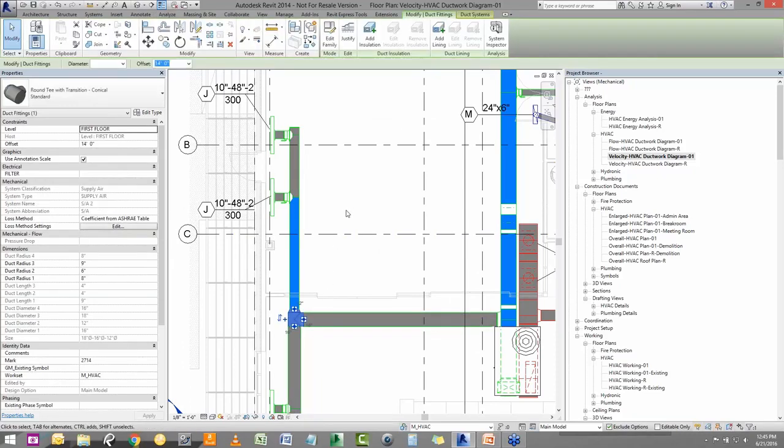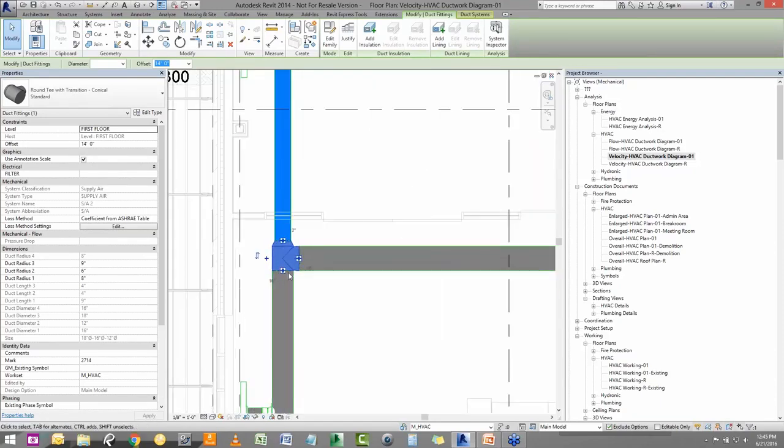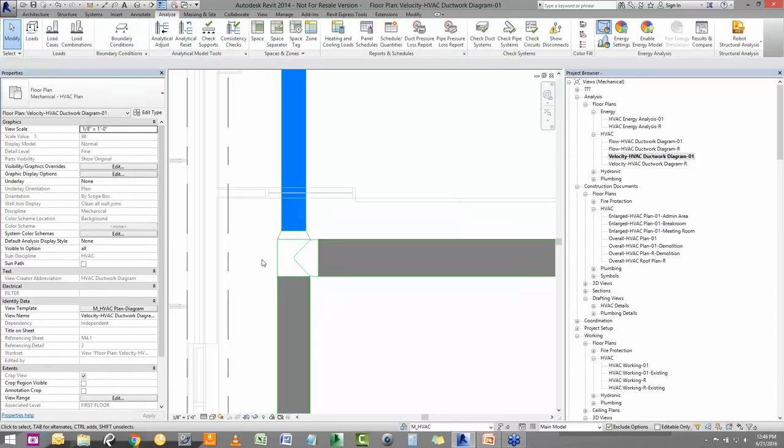Now when it comes to things like static pressure reports, this is where Revit runs into a little bit of a challenge, simply because it's very difficult for Revit to understand how this air flows coming this way on a T versus going this way on a T, or vice versa, or how it flows down these three different options. And that's because there are three different options.